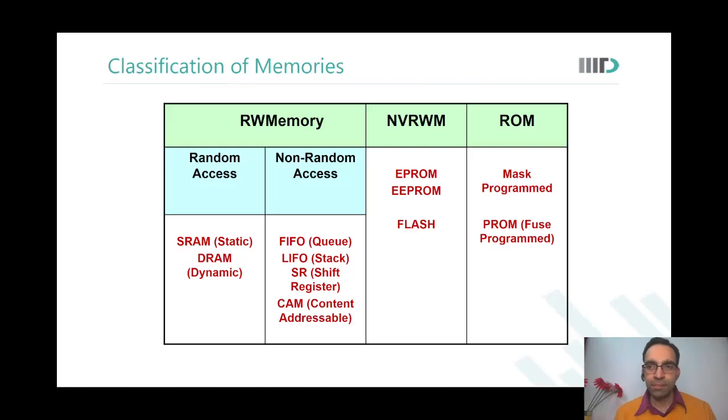Yes, sir. So when we operate the system at different operational voltages, naturally the frequency at which those different voltage islands operate would also be different. So there is one part of the chip which is operating at, let us say, 1 gigahertz, and another part of the chip which is operating at 800 megahertz. Now, if there is some information transfer that has to happen from one part to the other, do you realize that there will be some extra data coming from one side to be absorbed by the other side?